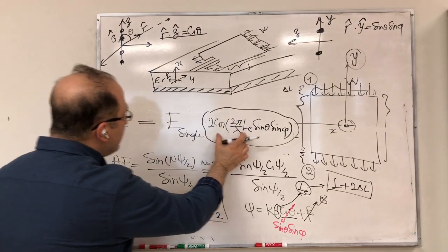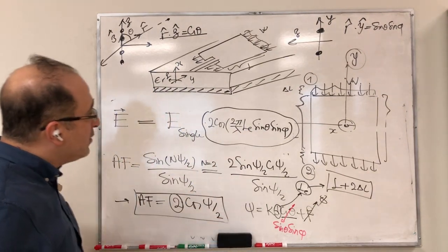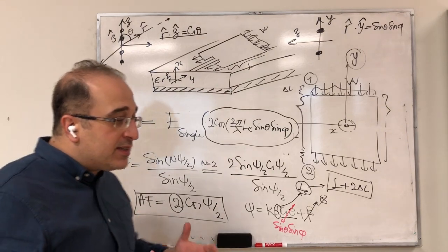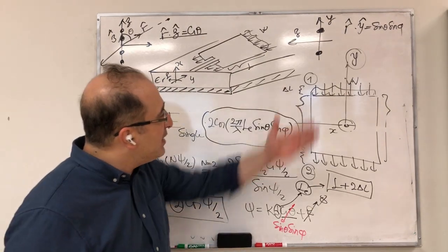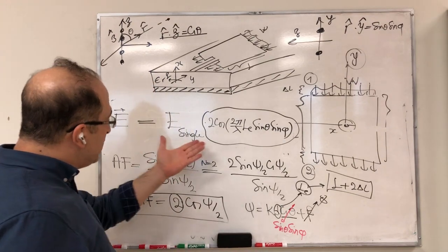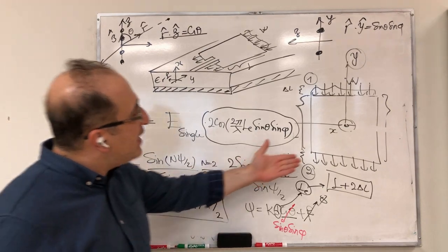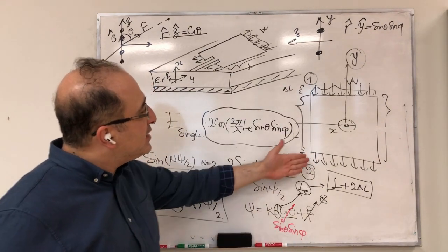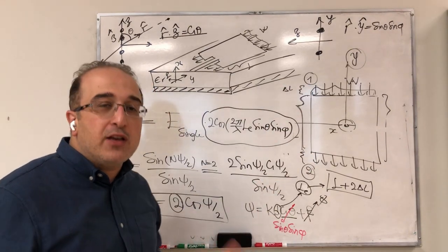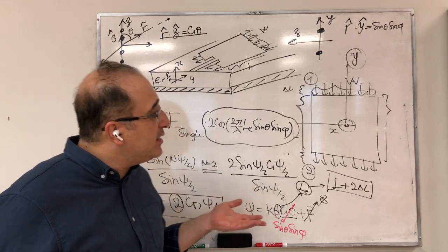So you can easily identify the presence of the array factor. And as I mentioned, if you want to see what's the effect of two elements in the directivity, you essentially need to go through calculation. But roughly speaking, because it's a two-element array, it has the potential of increasing directivity by about a factor of 2, which is 3 dB.